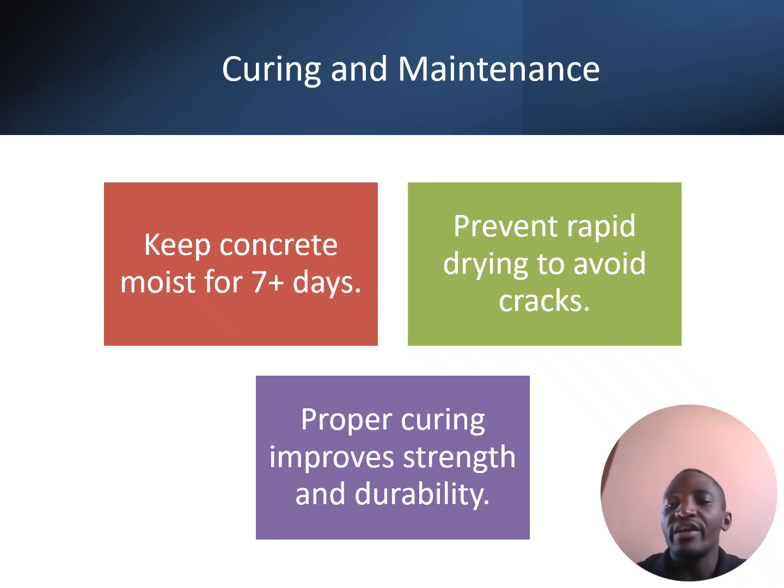Now let's look at the curing and maintenance of the concrete. For curing, you must keep the concrete moist for 7 days, in that case 7 plus days. Within 7 days, every day you must pour water on top of the slab or on top of the concrete to keep it moist for curing so that it can cure properly.